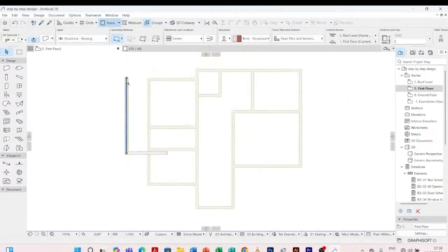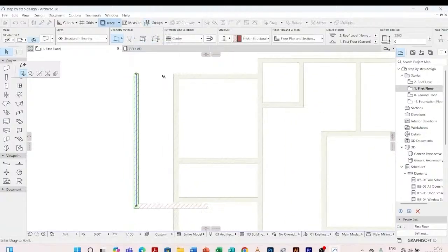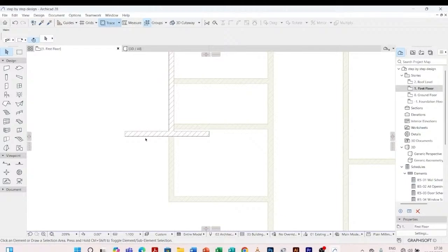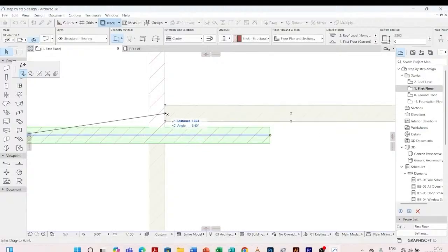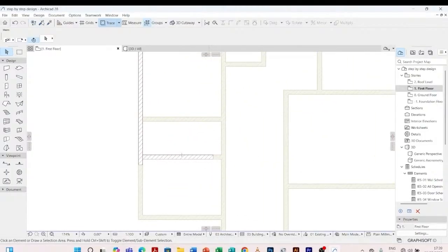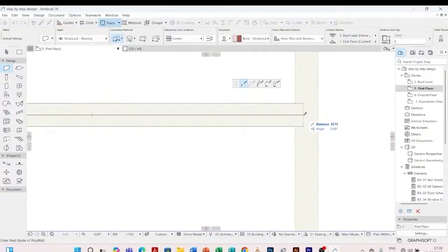So I can either just move back this wall, I come and click on this node up here, I can come and move it in the middle here, can come pick this, move it also with that. So I'm going to do the walls to trace from the ground floor. So I can come and I pick. This is our picking tool. I come and pick. So I'll draw a wall here. I'm tracing my ground floor.